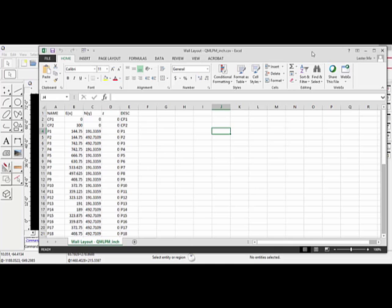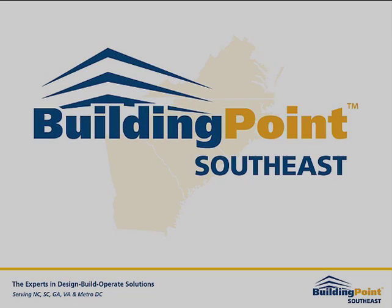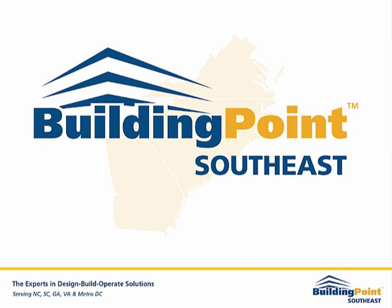So let's take a look at some export notes. Here we have some quick export notes to be aware of. The export, like I mentioned, is saved as a CSV file and can be opened in Excel. But what you want to verify is that the heading is exactly the same as you see here on the screen. You have the name as the first column, the X as second, Y, and then Z, and lastly the description. This will guarantee that it will import correctly into the QML layout tool or the controller. So this will conclude the tutorial on QCAD for QML800 Quick Mark Layout.